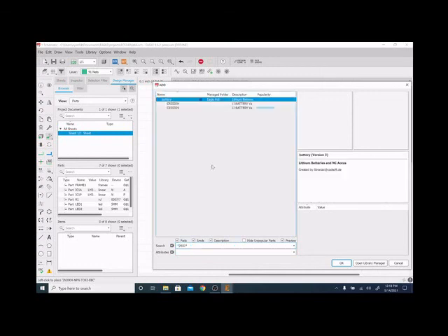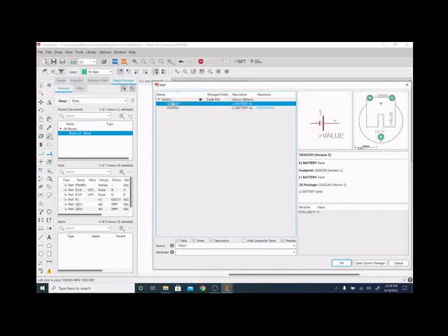If you search for that, although they have some, we don't have these style connectors, so we can't use these. So I'm going to pause this and show you how to import a custom library and how to make a custom part. We're probably going to start with the custom part first. We'll make the ATtiny85, and then I'll show you how to make the battery packs, or import a library for the battery pack.